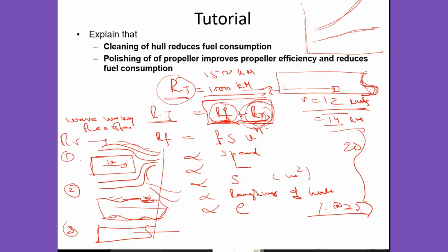At low speed, it does not have much advantage, except that it will add to the frictional resistance. So bulk carriers are not likely to have a bulbous bow, but on a high speed vessel this becomes an important item to add so that this component can be reduced. So this is why it is done.